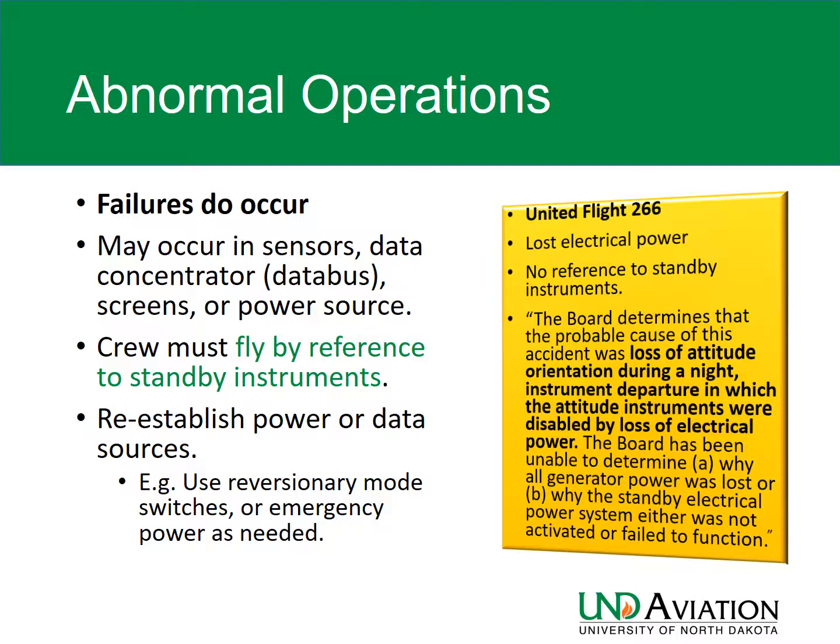The quote from the NTSB is, the board determines that the probable cause of this accident was the loss of attitude orientation during a night instrument departure in which the attitude instruments were disabled by a loss of electrical power. Now aircraft have more reliable backup and standby power, and standby instrumentation is often required to have an alternate source so that this sort of accident doesn't occur again. I do encourage you to review United 266.